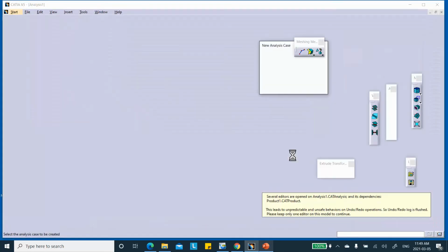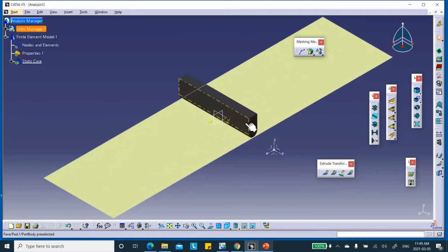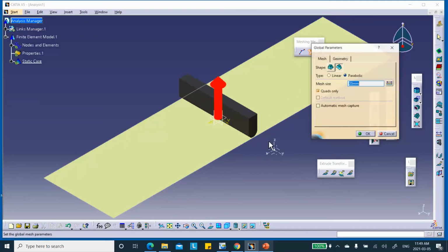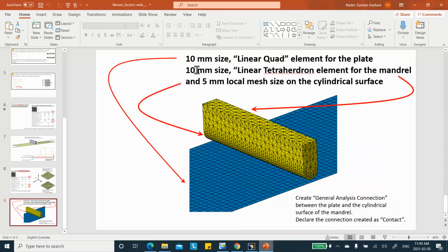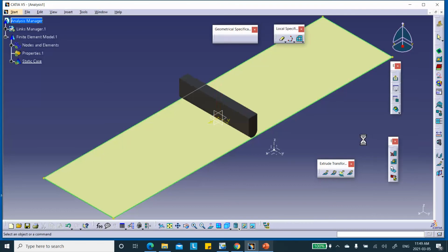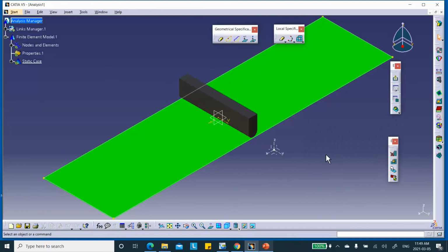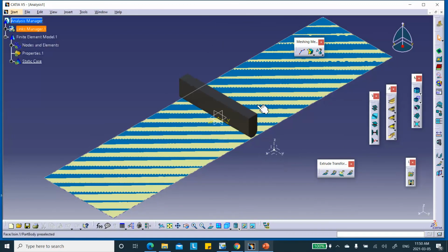It really doesn't matter. So I went to the advanced meshing tool. When you go to advanced meshing tool, this thing is not going to get meshed. Okay, you can mesh it, but I'm not going to do that here. But the surface I'm going to do. So here's a surface mesh here. On that surface, 10 millimeters, parabolic, quad only. Remember I had these things here. And then we say okay, and then you mesh it. This is what you have been doing for the last so many videos, 30, 34 videos. And then this is it, exit. Okay, it's meshed. We're going to look at it later.